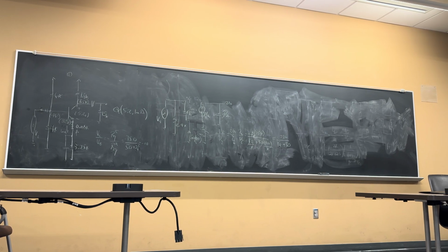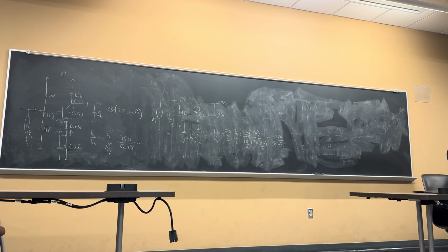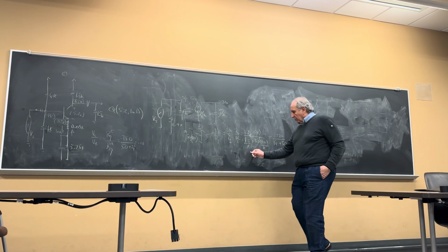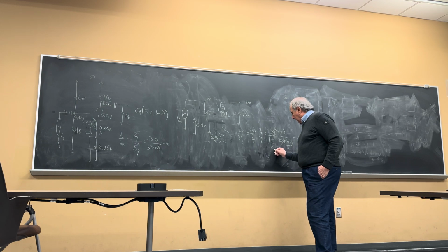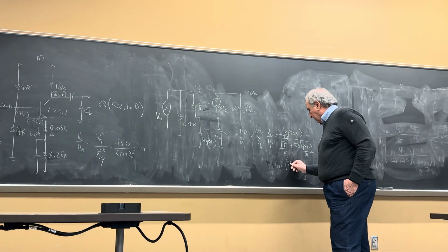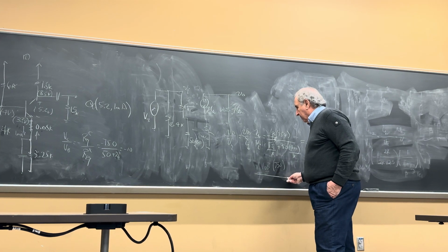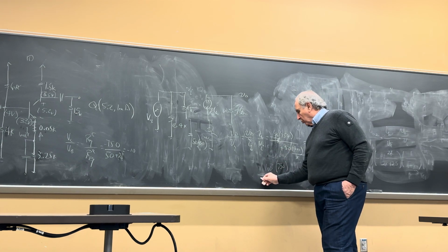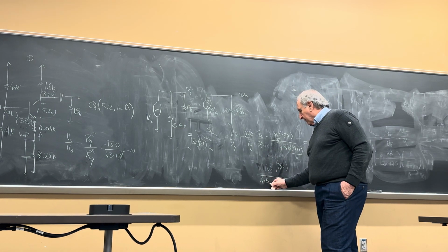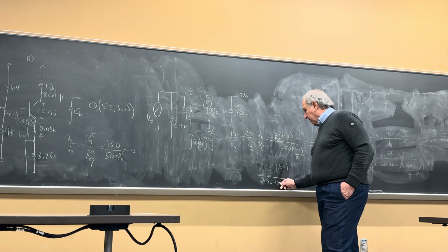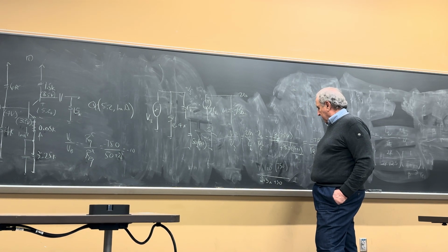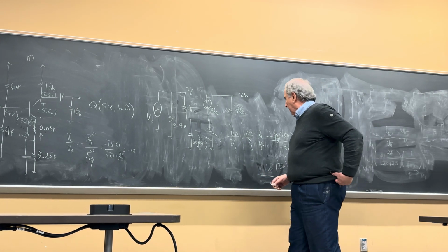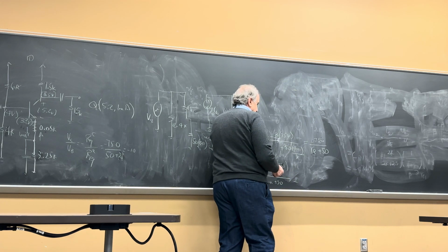So I calculated R pi. I didn't assume it's RE. So you should get minus 10. Okay, I said here's 100 times 750, divided by, no, so R pi is 2.5K plus 50 ohms. Right? So what I did is I used, no, this is times VT. So beta times VT over ICQ. Okay, that's why I got different numbers.